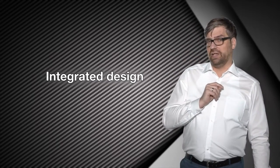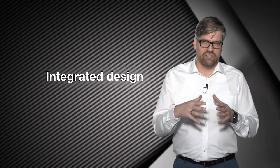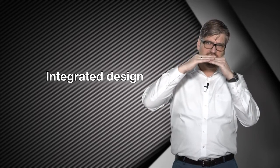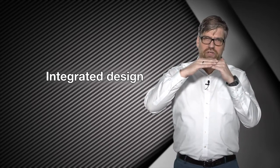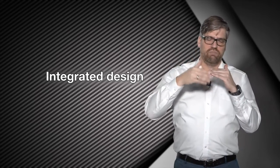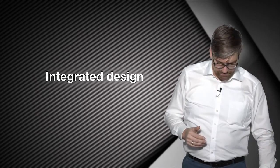Prefer integrated design is also important. When you have differential design, that means you have several parts, you have to join these parts. And each joining means that you have an overlapping length. And in this overlapping length, you have twice the thickness. And this increases, of course, your weight. And when your joint is not an adhesive joint, but a riveted joint, you have also, in addition, the weight of the rivets. So each joint means additional weight to your structure. So please try to make an integrated design where you have no joints.